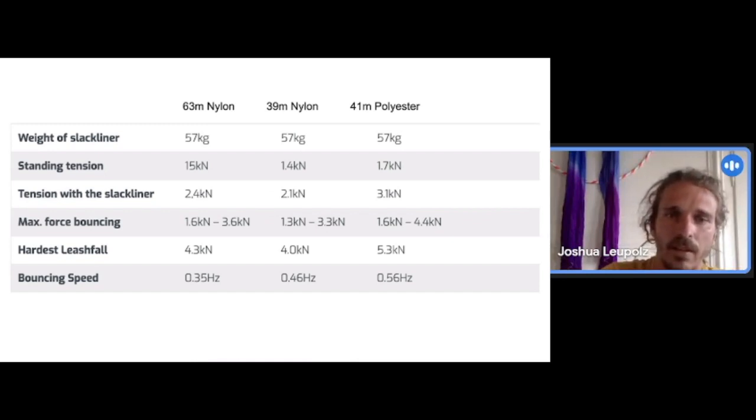Yeah, I think this is my last slide. So these are basically the values which are interesting to know, and therefore I would propose setting up a test method which looks like this: you put in your webbing, you make 2 markers on the webbing, just with some color pen marking 2 points on it, having some paper behind it with a millimeter scale, and then you cycle your webbing.